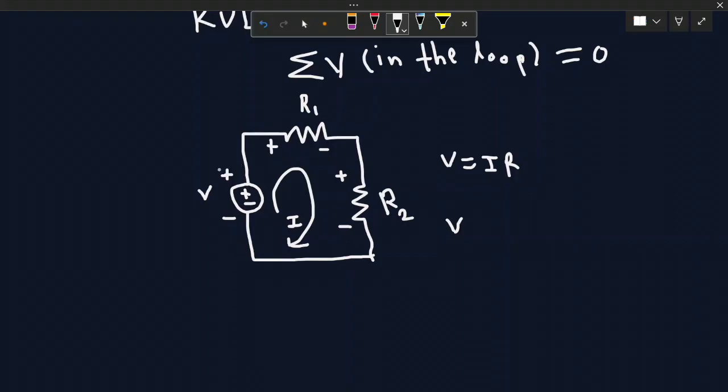So we have to consider the second sign, the ended sign. We have to consider the voltage source sign in the end while moving in a clockwise direction. So while moving in a clockwise direction, in the end, what I am getting at the voltage source is positive. So this is positive V. Move ahead towards the resistance while moving in the clockwise direction. In the end, at resistance 1, what sign am I getting? Negative. So this is minus IR1.